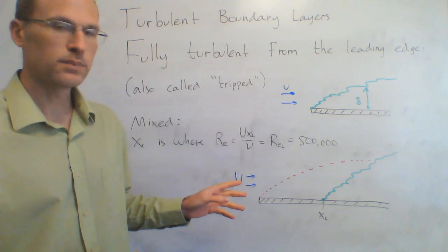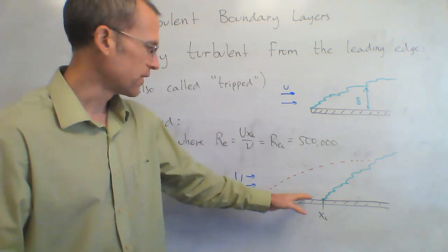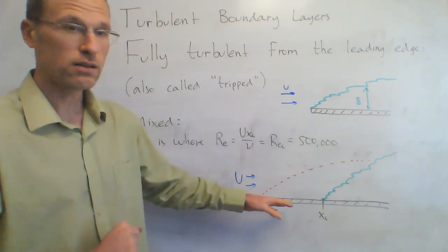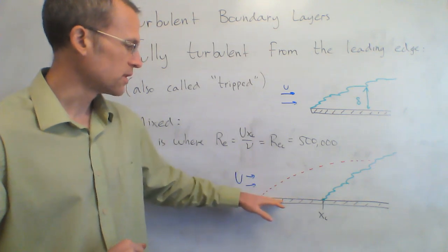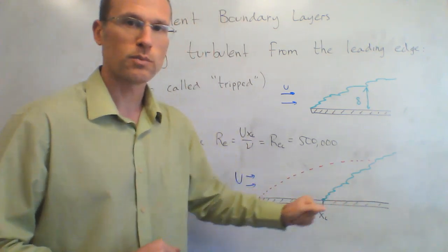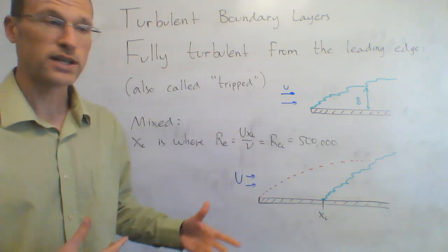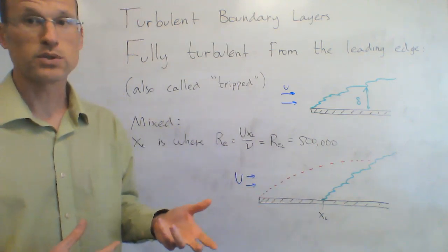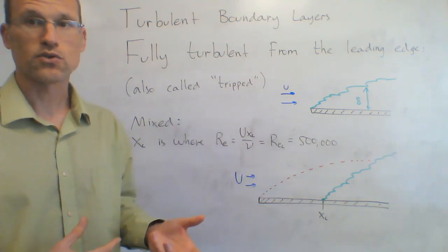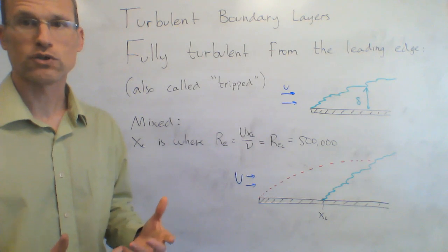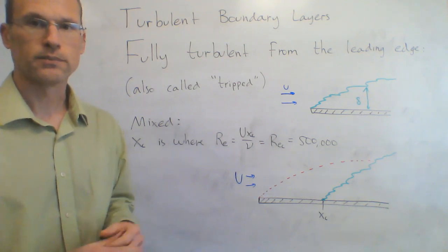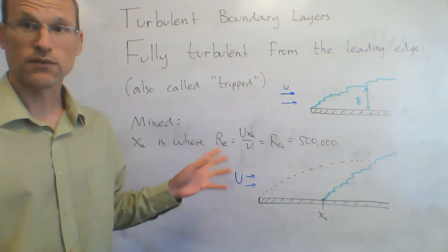Again, for shear stress on the plate, this can just be the laminar portion, that can just be the turbulent portion, but then when I go to calculate the force, I need the entire thing, and so that's the one I'm mostly concerned about. Also, I'm mostly concerned about force in general, the drag force. So for the mixed case, I need the force equation.